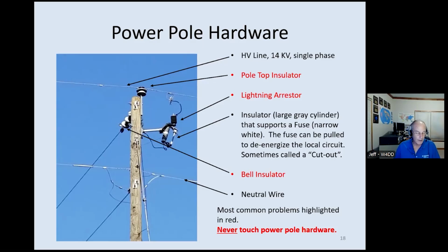But if you think about like an arc, if you walk up to an electrical plate after you've rubbed your feet on the floor, when you get near that ground screw on the plate, you hear a snap. So you're just listening to the audio portion. That's correct. The dish is an audio device. It hears that snap, even though you don't. And those dishes have audio gain on the order of 40 dB. They're pretty significant things. And the electronics has a high gain amplifier, 40, 50 dB worth of amplification. So it hears that snap, and it appears as a 60 hertz growl in the dish. Okay, thank you. Yep. Good question, though.